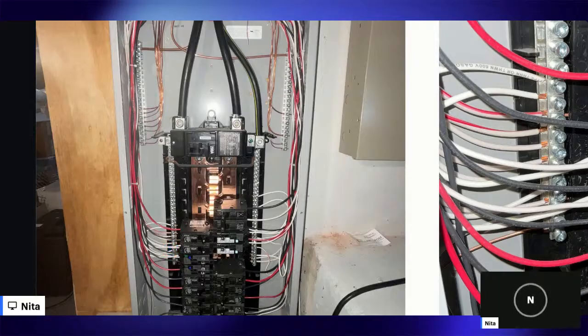A grounding neutral? Yes. You identify the bus bar by what's terminating on it, not by left or right. These panels don't come like this. When you buy the panel, you are literally buying just the box. The electrician assembles all of these bus bars however they see fit to be able to fit all of the wires and get your branch circuits out. So don't get caught up in left, right, up, down, or none of that. Identify the bus bar by what terminates on it.